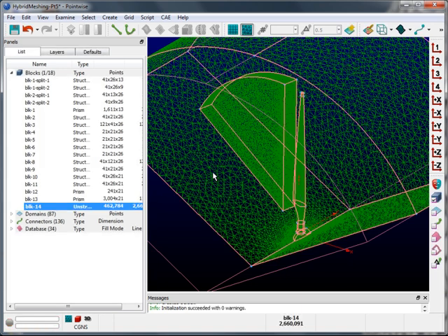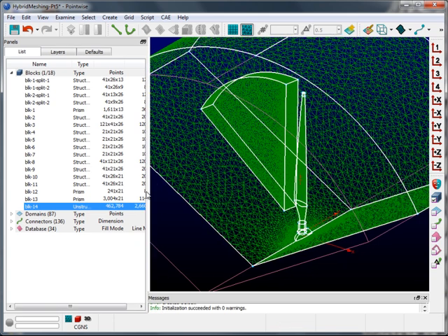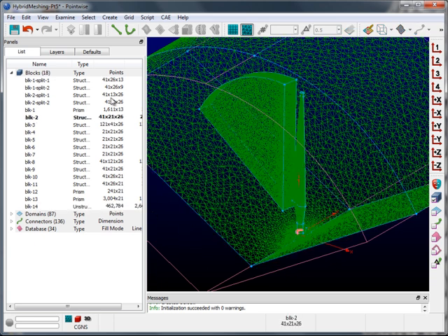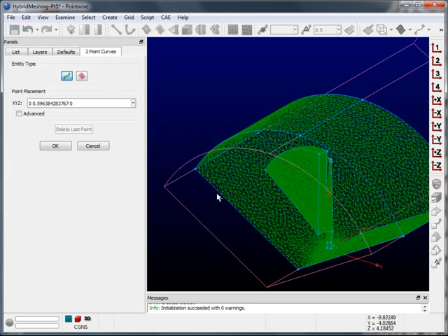Okay, so we've taken this unstructured block object that was uninitialized. We've initialized it. You can see there's about 2.66 million cells in it now, encompassing the blade and the wake block. So I'm going to set my average grid point spacing to 0.5, and we're going to construct the rest of the blocks in this near field region, just doing path extrusion.